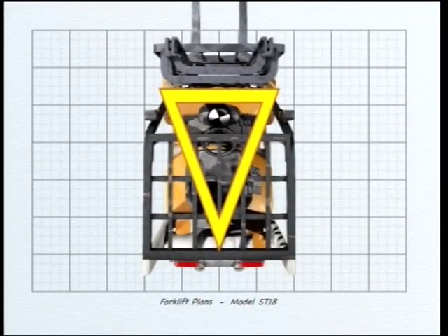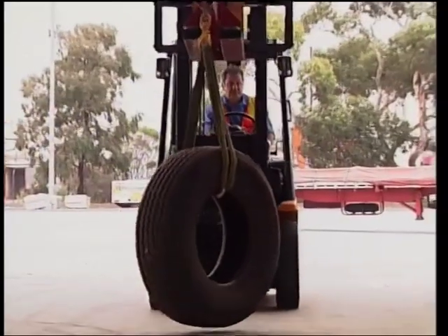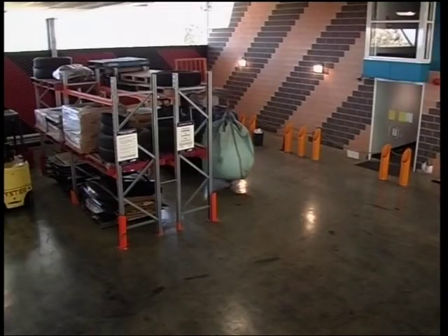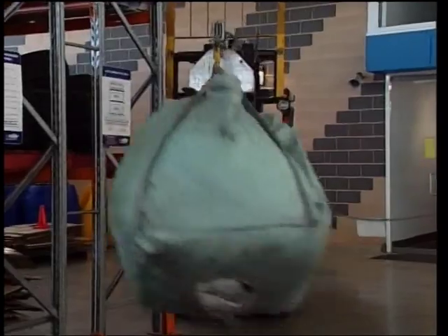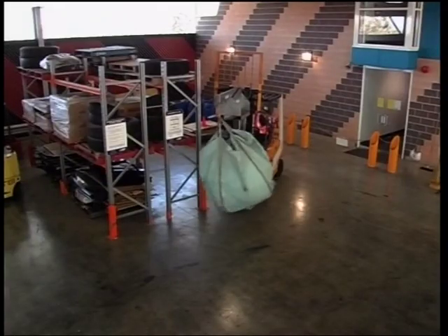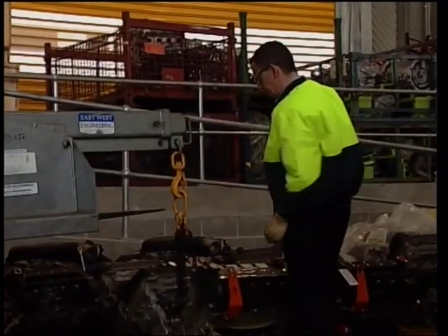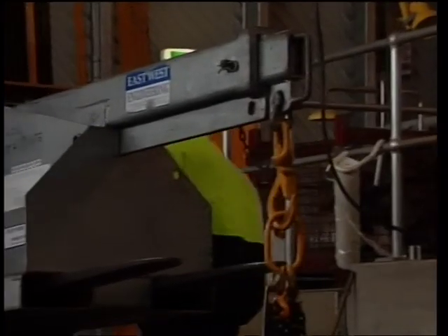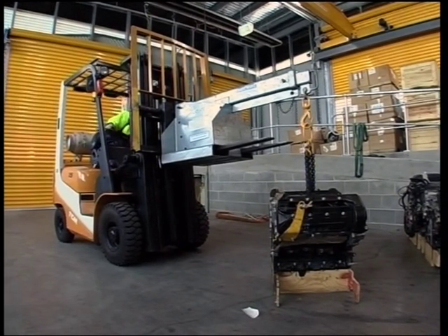Dynamic stability incorporates both longitudinal and lateral stability. When an industrial truck fitted with a jib lifts a freely suspended load, dynamic stability changes. As the industrial truck turns a corner, the load will normally swing out, decreasing the truck's stability. As with all attachments, the load capacity must be reduced when lifting a freely suspended load, and you must refer to your forklift supplier to update the new load capacity.